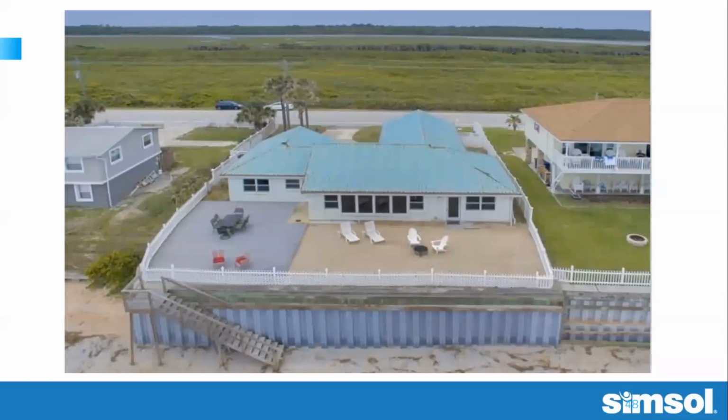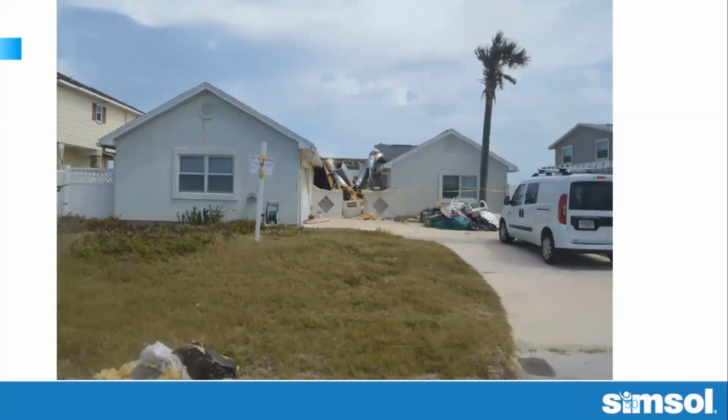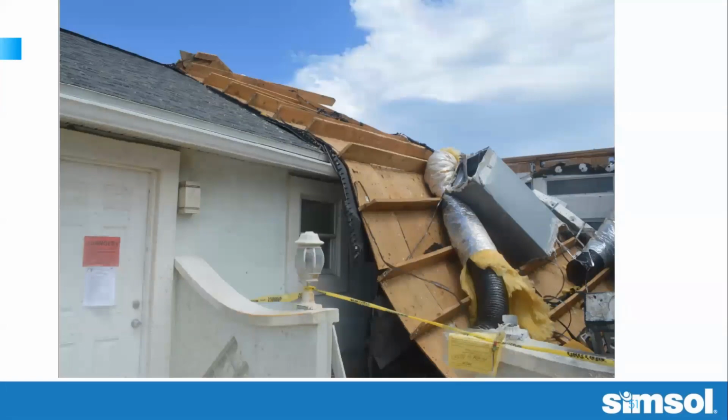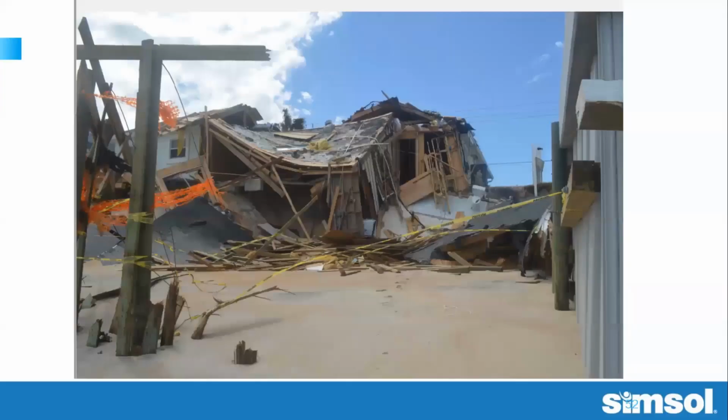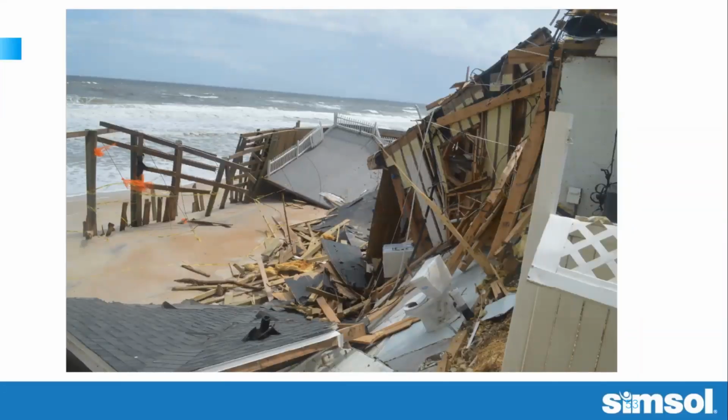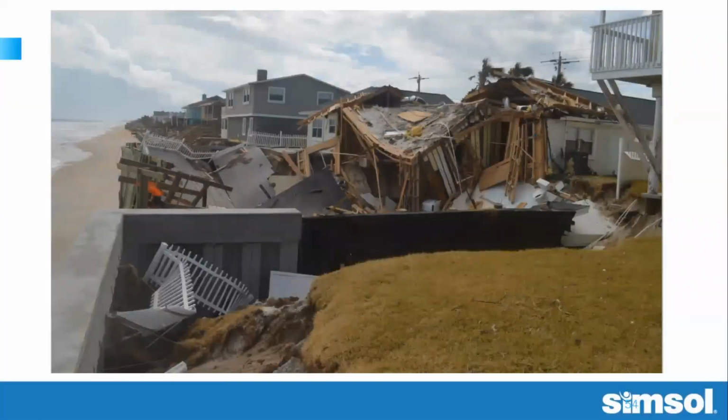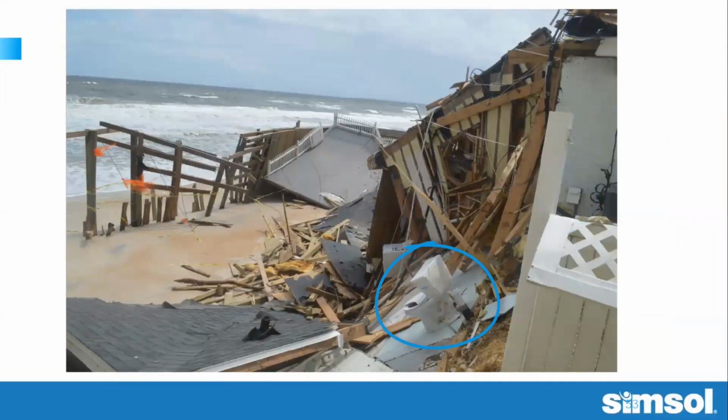This is a view of the house before Hurricane Matthew, and this is what the house looked like after Hurricane Matthew. Notice the back side of the roof slope is blown over the house, and here it is from down below. You see the sheet pile wall to my right. About 12 to 15 feet of erosion took place under the house from the surge, which caused the subsequent collapse of the floor slab. But this one also had some damage as a result of wind. However, most of the failure was from the surge itself. Notice too in the right corner of the photograph, whoever installed the toilet at the slab did a fantastic job, because as you can see here, it's still stuck to the slab.